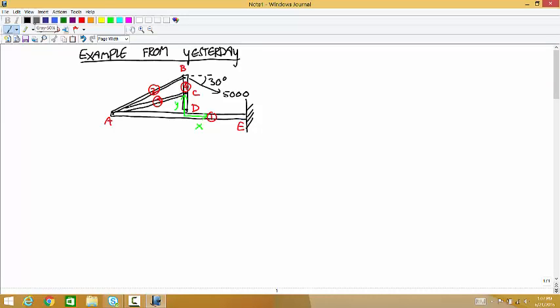Okay, so I'm going to do the free body diagrams, and then I'm just going to give you the answers and show what those look like as external loads. Save all the trouble of going through all the equations. But in a problem like this, I think the trickiest part, the place where you're most likely to make mistakes, is getting the free body diagrams right.